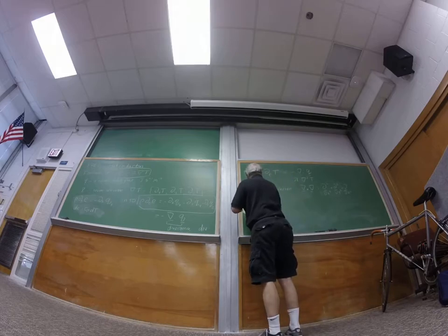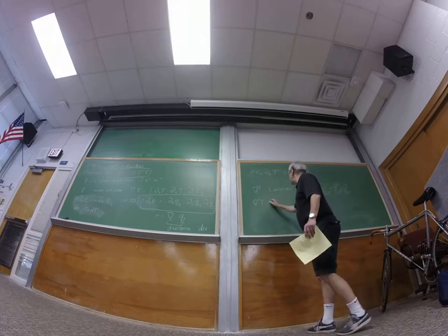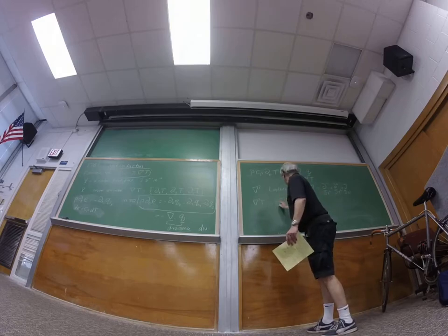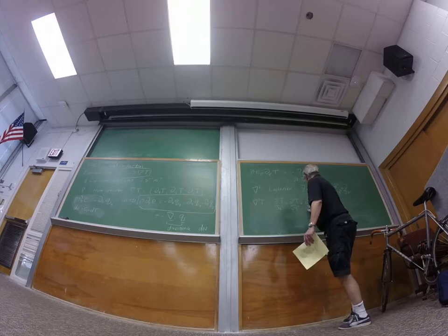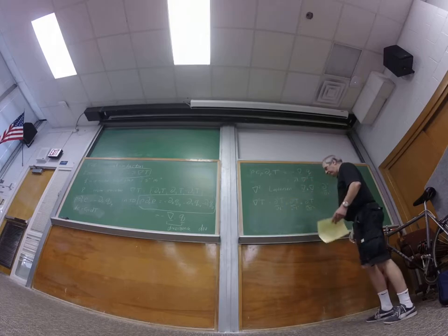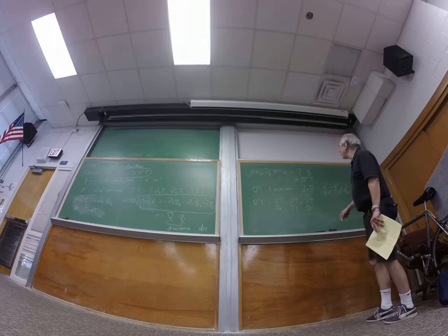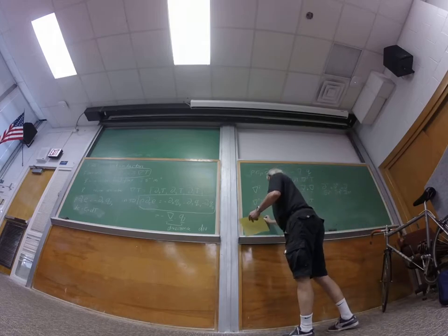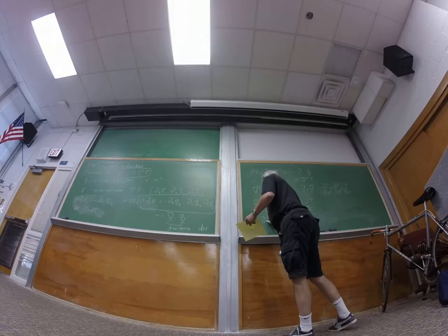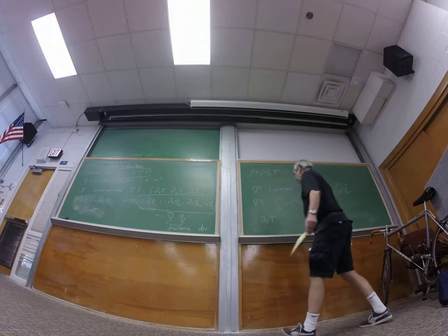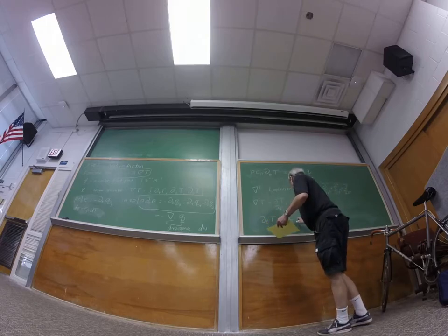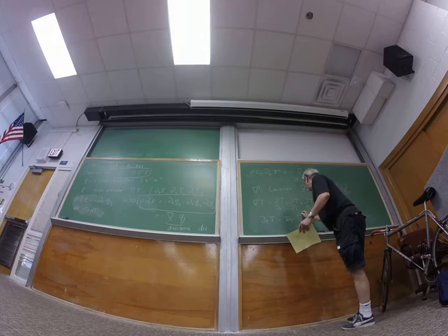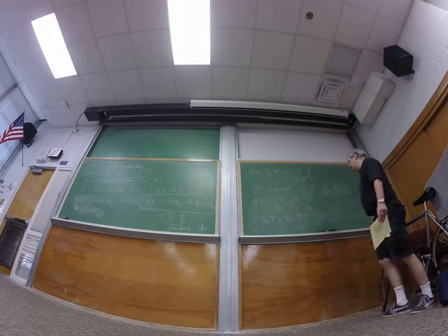So if we're going to write this out, then grad squared t would just be the second derivative of t with respect to x, plus second derivative of t with respect to y, plus second derivative of t with respect to z. Okay. So if we stick all those things together, then we get the equation that I was trying to get to, that the partial derivative of the temperature with respect to time is just some object, some number, times the Laplacian of the temperature.